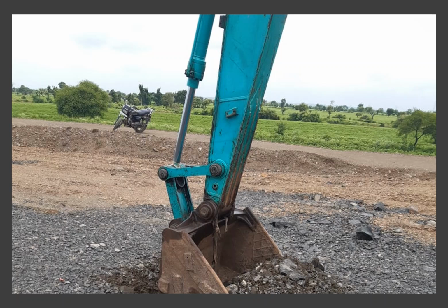How do we check the performance of the rock fill embankment, or how do we check whether the construction of rock fill embankment is meeting the specification requirements established in MORTH or not? For that, you need to have a random check on the working embankment layers. You can collect samples by using the excavator's bucket as shown in the photograph.